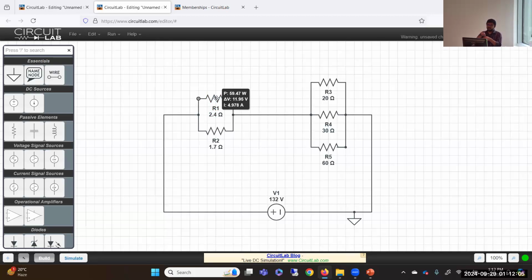So when you rotate, you need to make sure that you rotate 4 times, or you can just rotate once clockwise and then flip horizontally. That will do it. So this should be your positive terminal of the resistance, right? Because the current will flow in this direction. The positive terminal of the resistor should be here. You need to make sure of that.